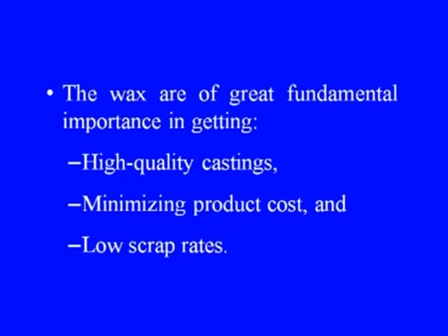The shrinkage characteristics of waxes and their influence on the final dimensions of the casting are to be considered. The wax is of great fundamental importance in getting high quality casting, minimizing product cost and keeping scrap rates low.